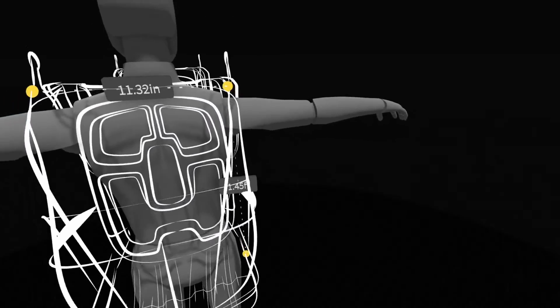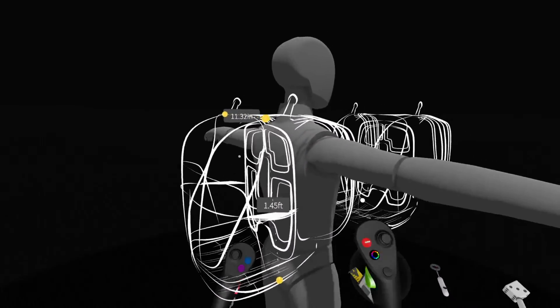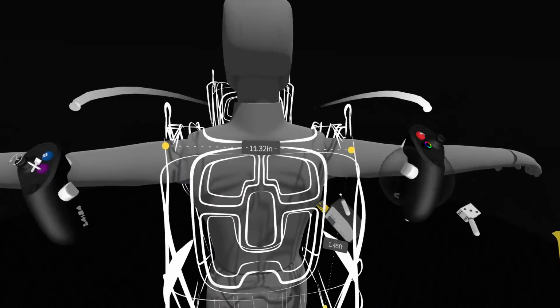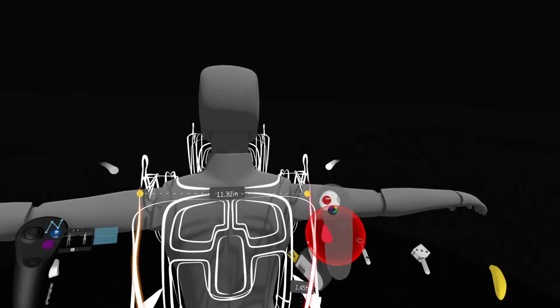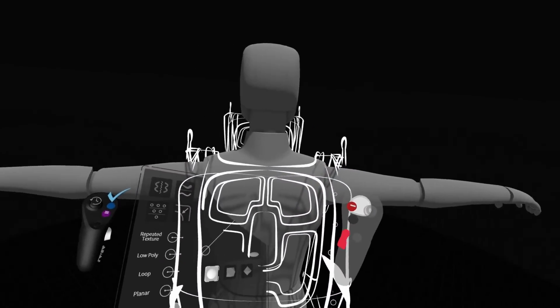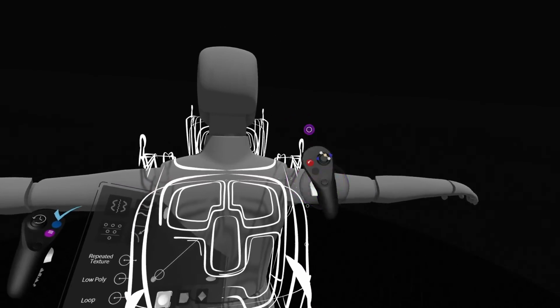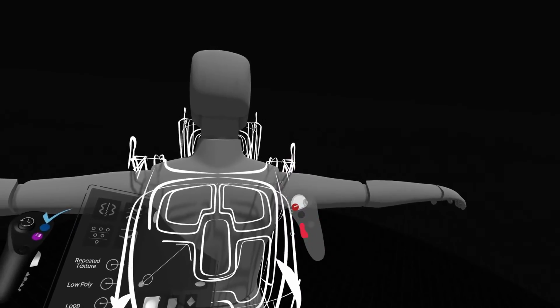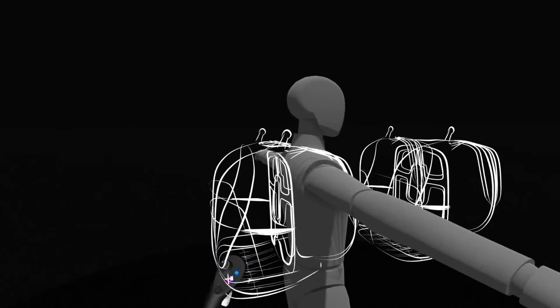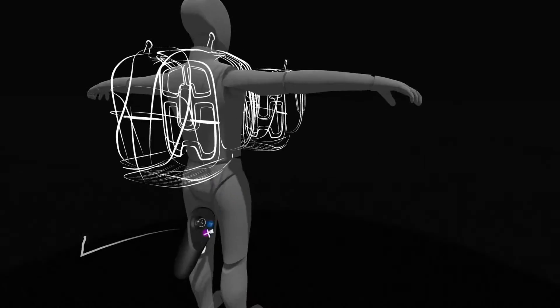And so if I've got actual real world dimensions that I'm working off of and I'm thinking, okay, this needs to be actually within this certain amount of width, then I can take these strokes and start moving them in, moving things closer together and getting it the way that needs to be in the real world. And so you can even check your design in that way in Gravity Sketch.